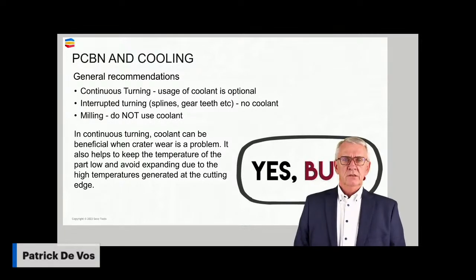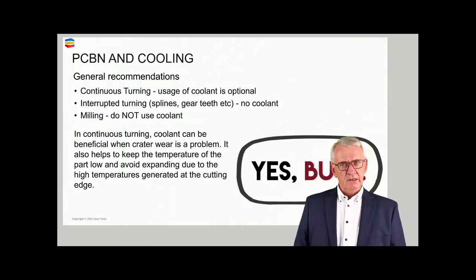Cooling is possible, but you should question it. Do I really need it? And there are a number of situations. Think of it: I need my heat, I need my temperature to soften my workpiece material. There are a number of applications, I think mainly in interrupted cutting and so on, milling applications, machining of splines on a lathe and so on, where I would say do not use cooling. No cooling should be your basic choice.